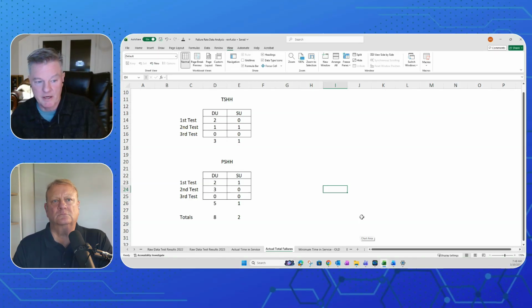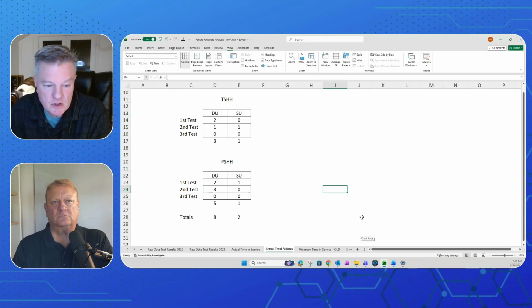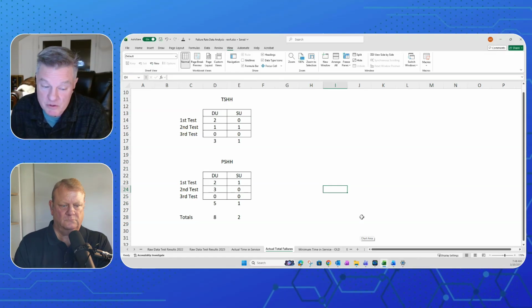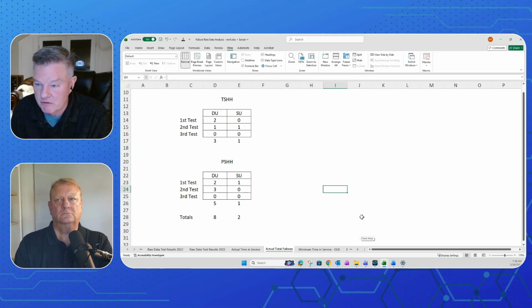We could do a project. We could implement it. The platform is a database. So if I update a failure rate in one place in the hardware standards library for 500 pressure transmitters, I just updated 500 SIL calcs. I don't have to go to each one. I don't have to touch them. I just run reports on pass fail.